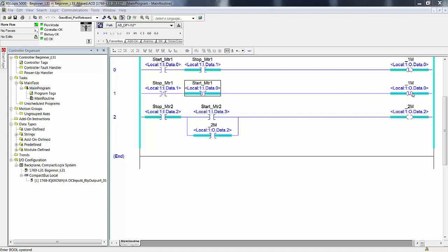Electrically, you have two coils. Here you only have one, but if this were an electrical circuit, this would be a stop push button, a start push button. Now that would be normally closed if this was an actual push button, electrical circuit. So as long as you're not pushing a normally closed, it's closed and you have continuity. When you push this button, the normally open closes, energizing this coil.